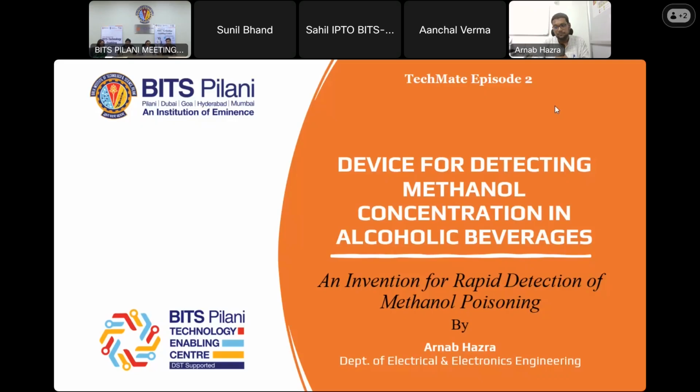Okay. So apart from the beverage industry, what could be the other industries that can use this kind of sensor? Basically, this particular device is based on a novel technique, the dielectric change technique. Where the target analytes are high in concentration and have quite a high dielectric value, this sensor can be used. I can give you some examples. It can be used for humidity detection, because humidity has quite a high dielectric constant. And other than that, different volatile organic compounds which have relatively high relative permittivity, we can use it for different applications. But if the concentration level is low, in the lower ppm or ppb range, this sensor will not work.